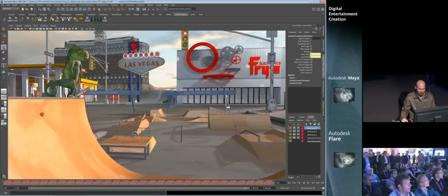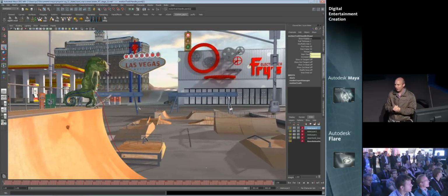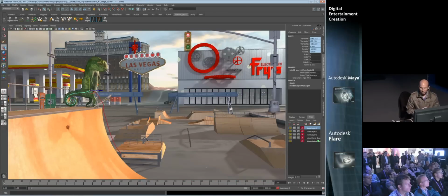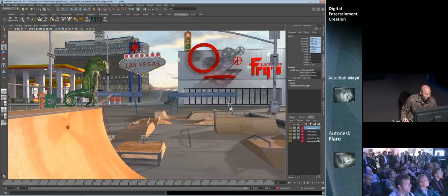The other thing that Bullet brings to the table that's interesting is a variety of constraints that you can use. By having constraints with rigid bodies, we can create ragdolls. That's what we want to do on this character's tail. I want to make a ragdoll simulation to give me that dynamic secondary movement. So we'll go ahead and create the ragdoll.